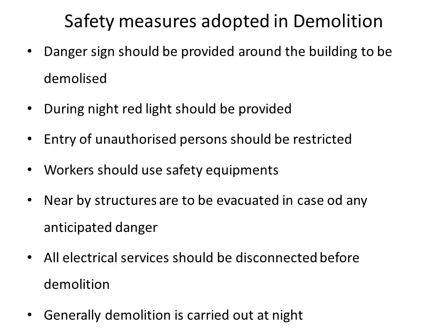Then the electrical supply to the building and also to the nearby places should be cut off before the demolition is started. Commonly we start the demolition work at night. This is to avoid huge crowds, and we can also prevent disturbances to the surrounding areas if we do the work at night. So that is why we do the demolition work at night.